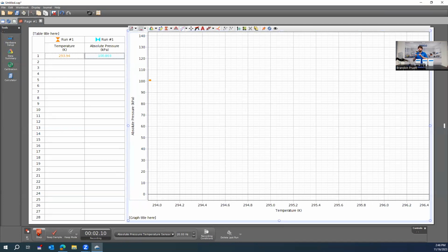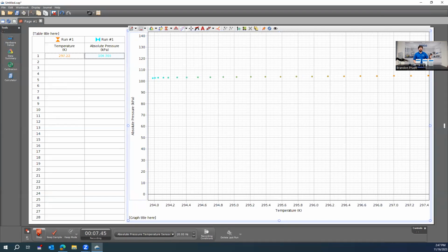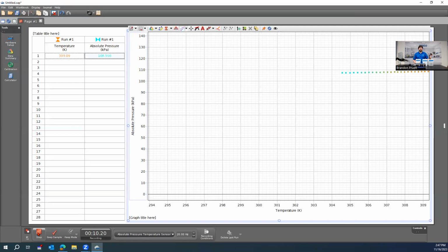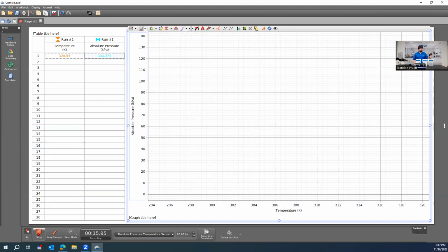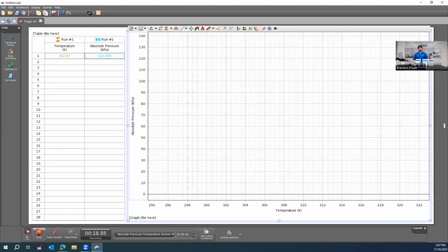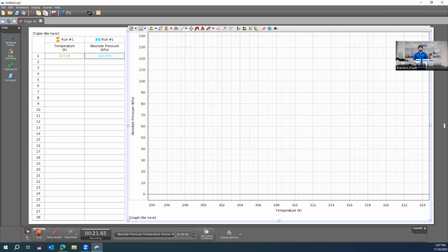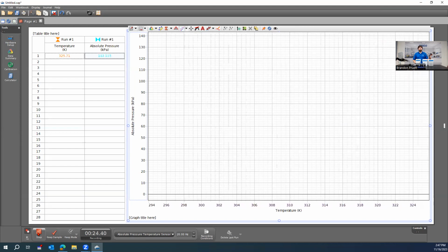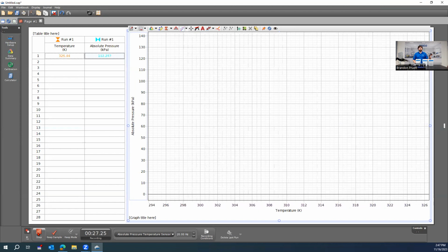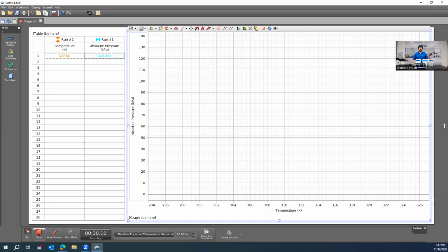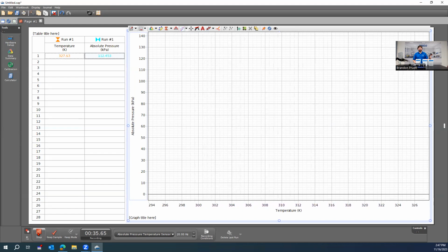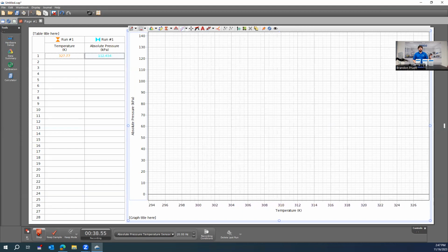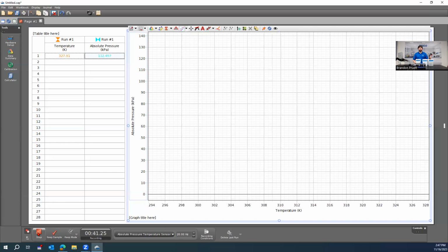So we'll do the hot one first and fully submerge the sphere, and keep it submerged until the pressure and temperature values have stabilized. This may take up to 30 seconds, possibly more. We're just waiting for these values to stop, well, in this case, increasing to a point where they are just fluctuating between a range of values.